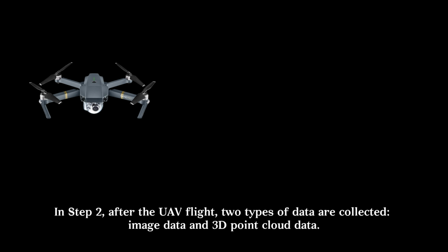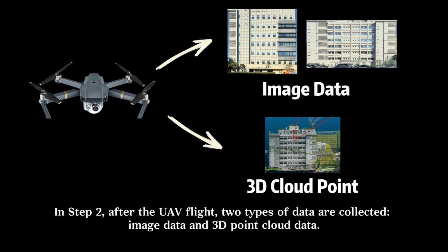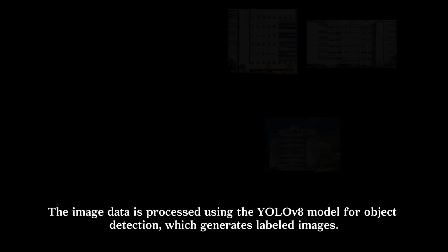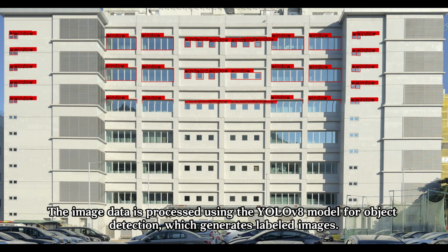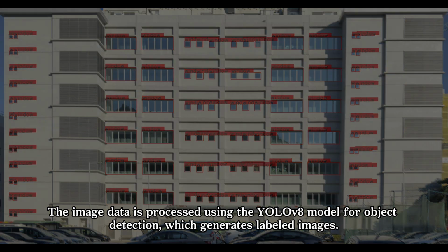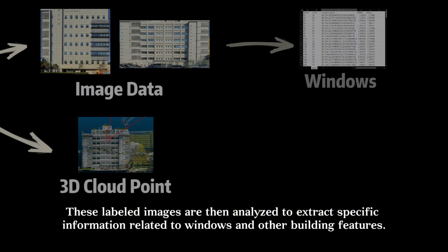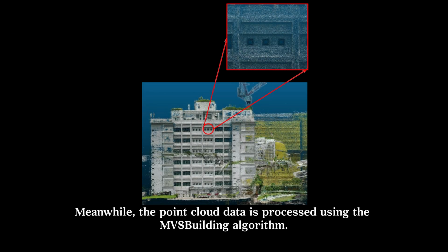In step 2, after the UAV flight, 2 types of data are collected: image data and 3D point cloud data. The image data is processed using the YOLOv8 model for object detection, which generates labeled images. These labeled images are then analyzed to extract specific information related to windows and other building features. Meanwhile, the point cloud data is processed using the MVS building algorithm.